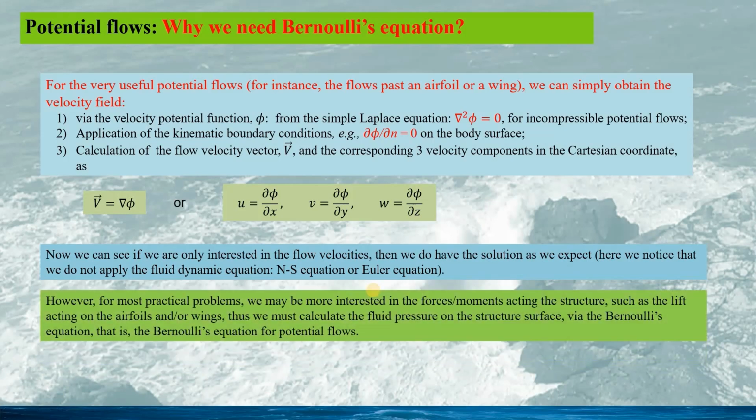However, for most practical problems, we might be more interested in the force and the moment acting on the structure by the fluid, such as the lift acting on the airfoil and or wings. Thus, we must calculate the fluid pressure on the structure surface. This can be done using the Bernoulli's equation. Here, the Bernoulli's equation for potential flows.